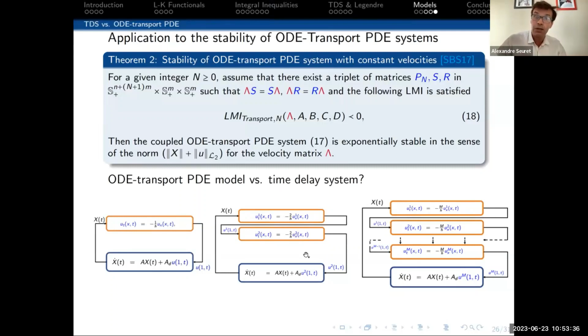So in that case, you are doing some kind of discretization process of your system, and you are creating a Lyapunov-Krasovskii functional that is discretized almost in the same sense of Keqin Gu's result of discretization, and also in the sense of delay partitioning of James Lam and so on. So by doing that, just changing the models, you have the same LMI and you are applying a discretization process.